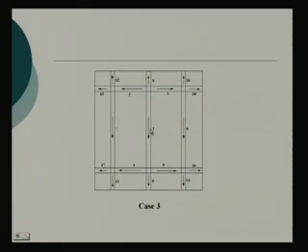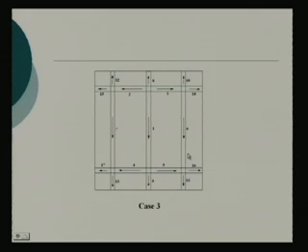Now, whenever a complicated drawing comes where you have 20 longitudinal members and 10 transverse members or whatever, based on this you show the sequence. It is to be shown, and only then will the welder follow, and only then can you expect the deformations to be controlled.